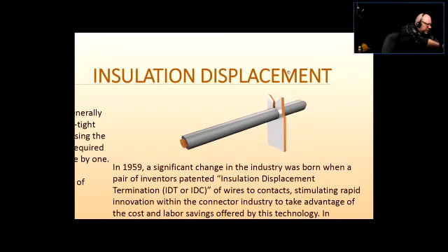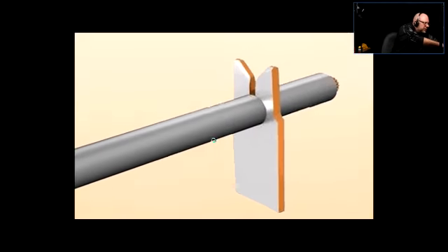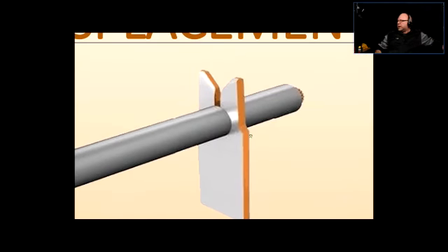This is what the basic form of insulation displacement connection looks like. Here's a connector with some sort of a slot there, knife-shaped connector, and they are not spring-loaded, but they're pretty close to each other. So they can be separated a little bit upon pressure, but then they retain the memory and come back to the original shape. So with the IDC, we don't strip the cable. Insulation is an integral part of the whole undertaking, okay?